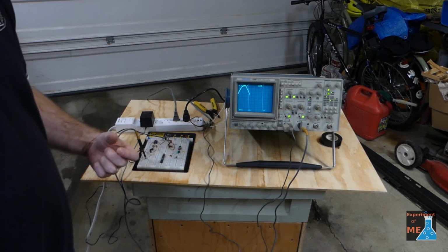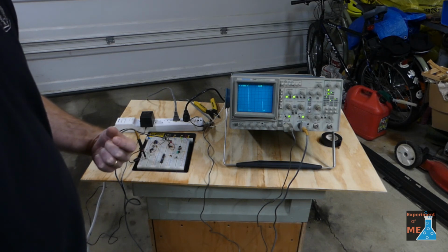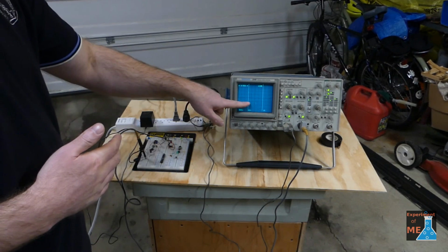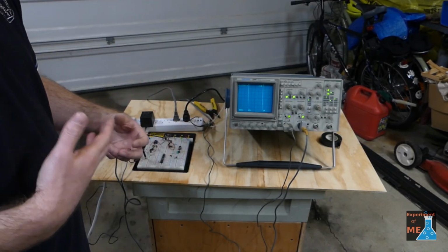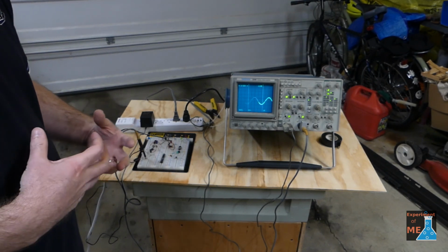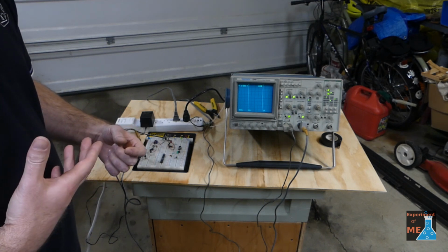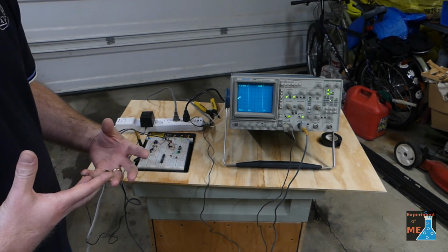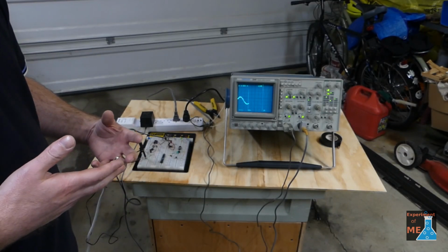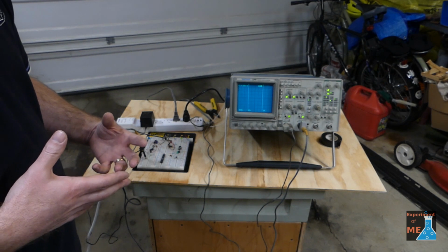But cameras see that because the shutter time is a very small window, and if it happens to line up with this dark period, then it will see that as a dimming environment. And so that's why when you take slow motion video where your camera is sampling faster, you can get these effects where the video goes dimmer.